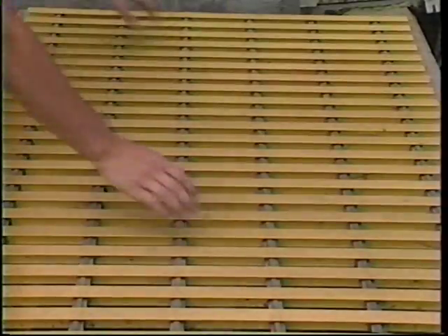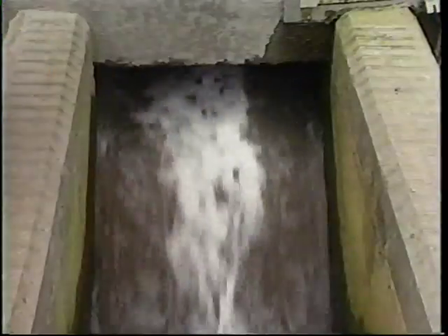Finally, let's take a look at the underdrain system. It is this system that supports the media, facilitates the collection of the wastewater under the filter media, and allows for airflow up through the media. The underdrain system should be kept free of debris to allow the wastewater to flow unrestricted out of the trickling filter. If wastewater backs up in the underdrain system, it could trap off airflow and lead to septic conditions within the filter.